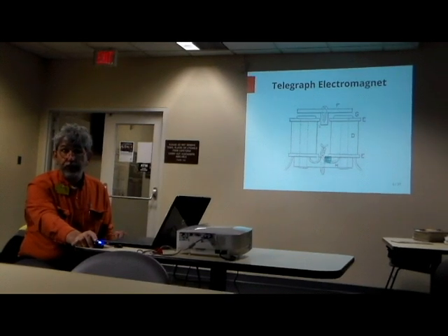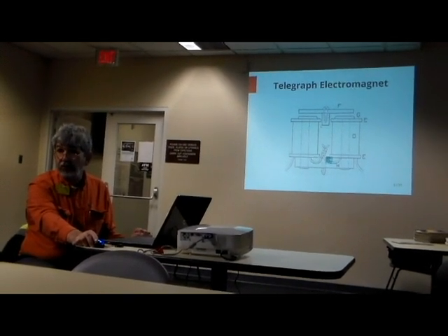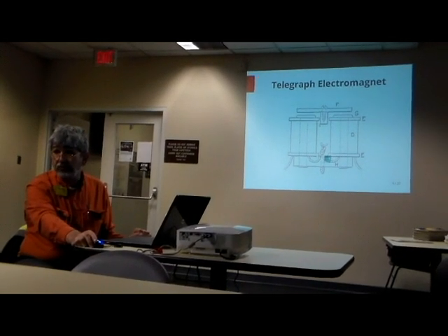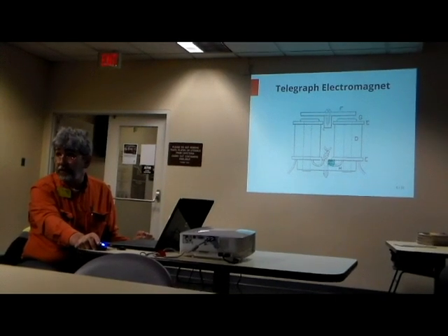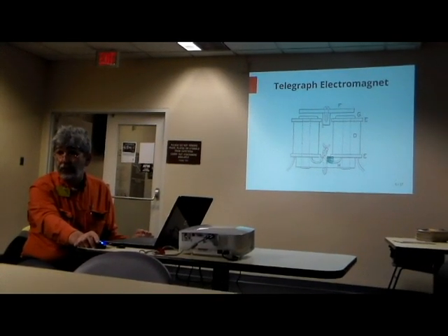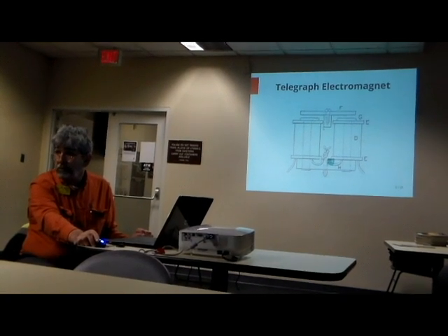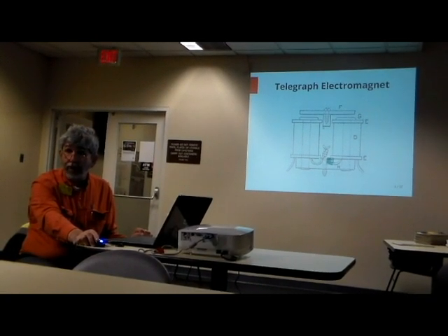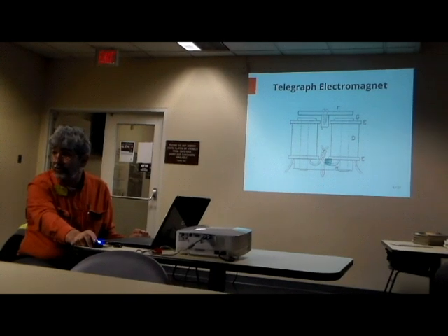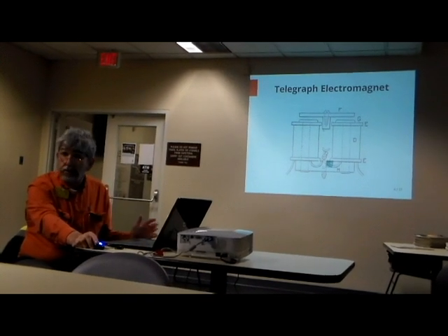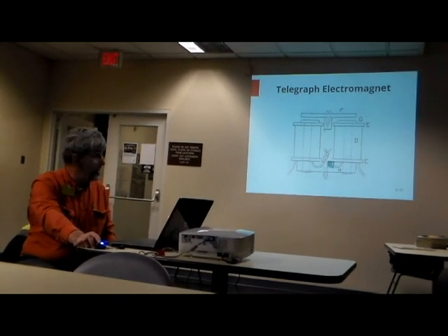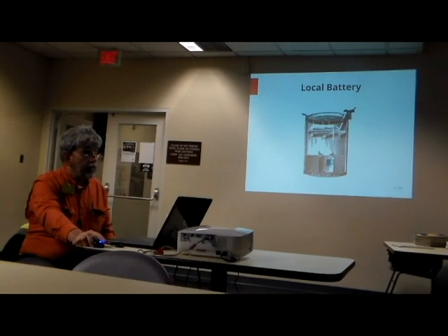Many railroad shops, for instance, did this a lot. They could take one sounder and convert it to roughly 1/4 of its previous value by wiring the coils in parallel, and that's the only change they had to make. So it's just a good thing to know about them.